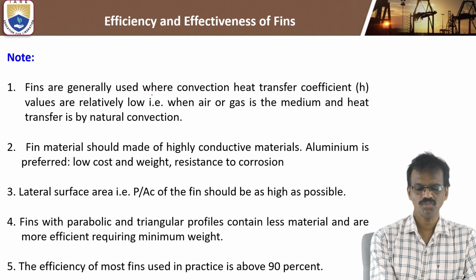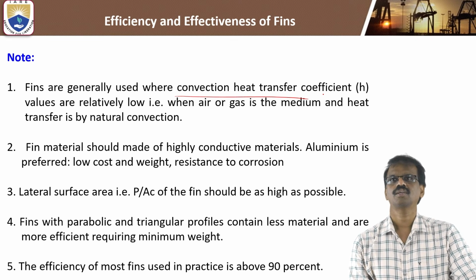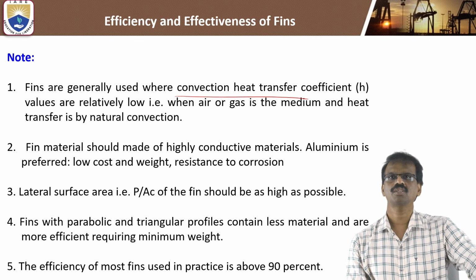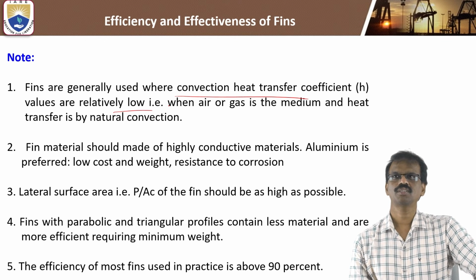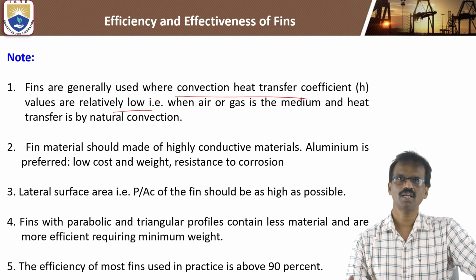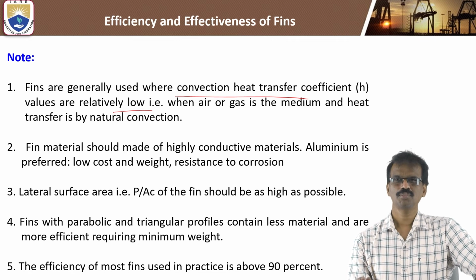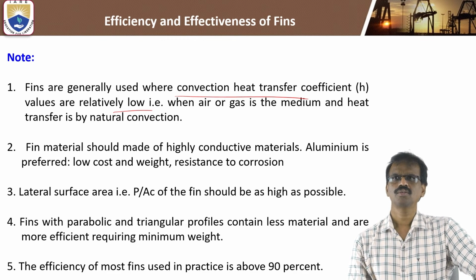Pins are generally used when convection heat transfer coefficient values are very low. To enhance the convection heat transfer rate, we add the pins, mainly used for air cooling systems.